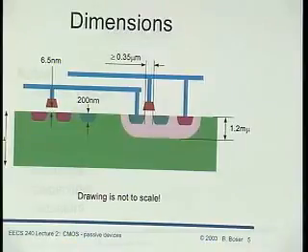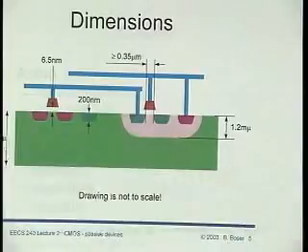Okay. So, well, that's a good perspective for an analog circuit. Always think about the trouble first, right? Yeah, you're absolutely right. This thing is going to latch up on us, right? Of course. So we're going to use an epi substrate or whatnot, or put a lot of these contacts all over, or probably both. Right?